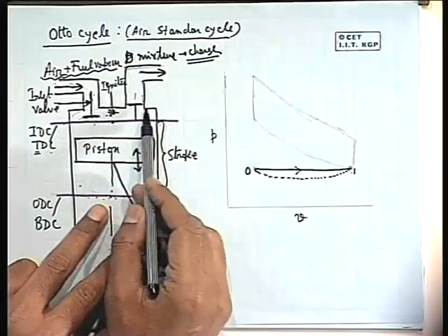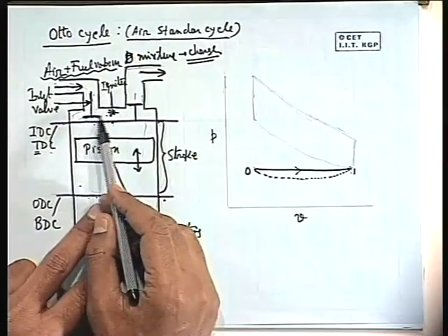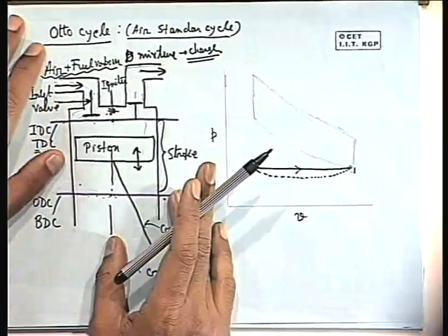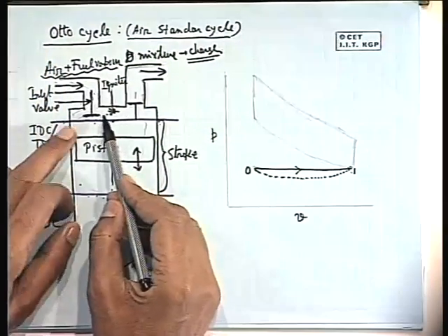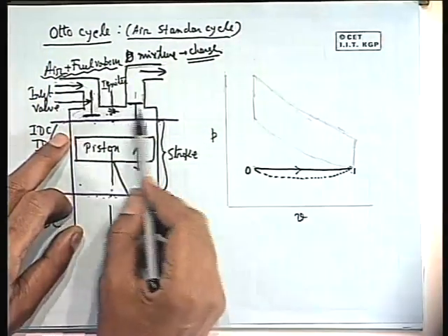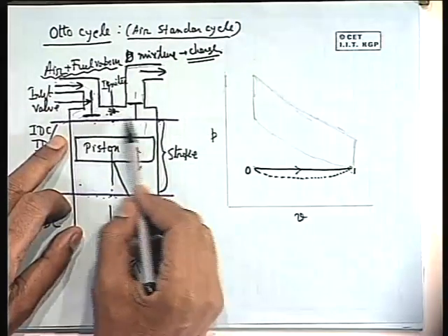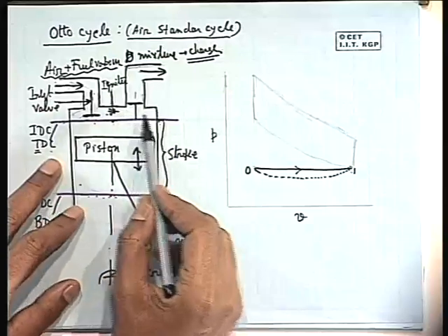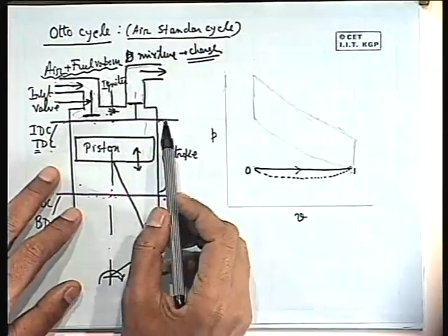So this is an exothermic reaction, though loosely many people say that it generates heat or liberates heat. That is the wrong terminology, which I will make clear afterwards. An exothermic reaction does not mean that it liberates heat, because the question of heat does not come here. This is a closed system which is insulated, so there is no question of heat, because heat is an energy which is in transit because of a temperature difference.